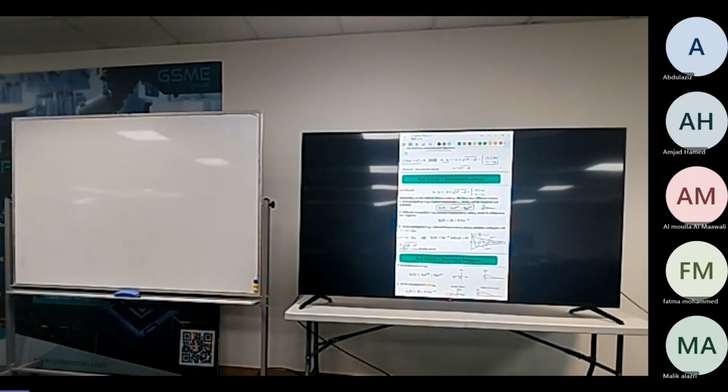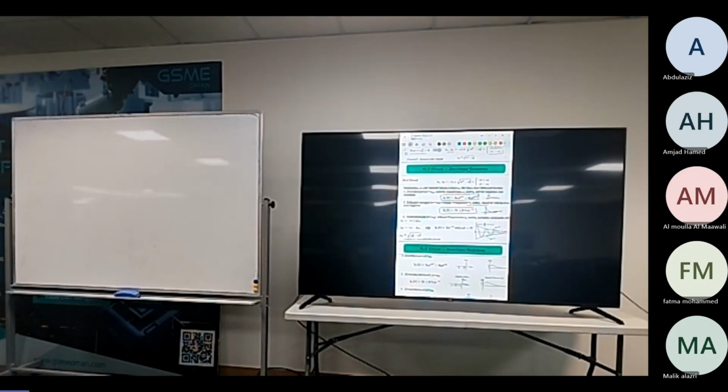When S1 and S2 are equal, we call it a critically damped circuit. Its response is something like that. It's a bit faster than overdamped. And when S1 and S2 are imaginary, we call it underdamped. It cannot settle exactly there. It goes a bit lower and comes back, and after a while it goes to zero.